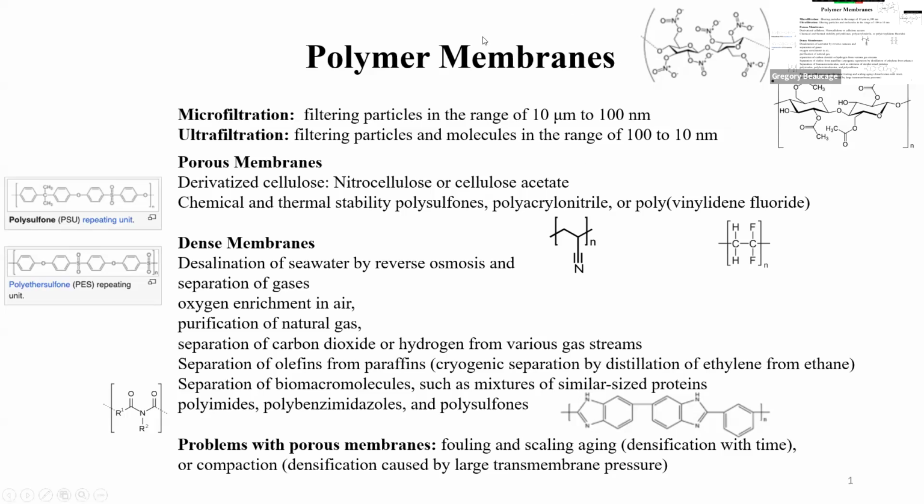So basically, the idea of microfiltration, ultrafiltration, you get into this region where the gas or ion or whatever is being separated, the transport regime changes from a continuum to this molecular scale transport. Right, so that changes the behavior of the membranes. So those are all more or less porous membranes, and then there are dense membranes, which would be just a film. So this is like reverse osmosis, where you're doing molecular scale or atomic scale separation, right?